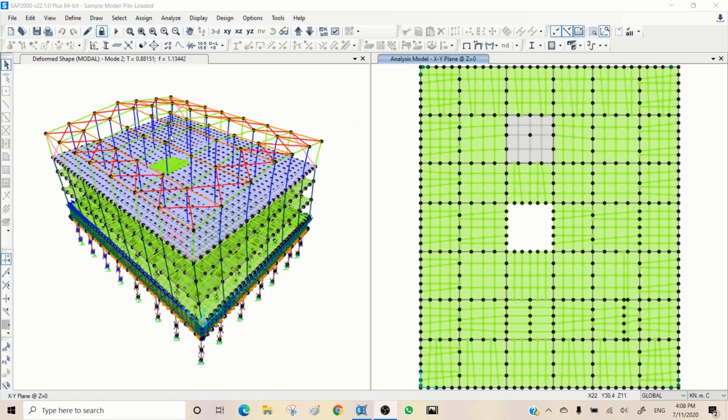If you remember, we had some issue about the vertical displacement around the lift. The reason was the shell were not connected to the wall properly. So they were meshed, but they were not edge constrained. Always my suggestion is use the edge constraint for vertical and horizontal shell elements. Even if the joints are exactly matched, my suggestion is do it. There is no harm for that. But definitely that can help you to ensure the compatibility of the formation and transferring load properly to the wall.